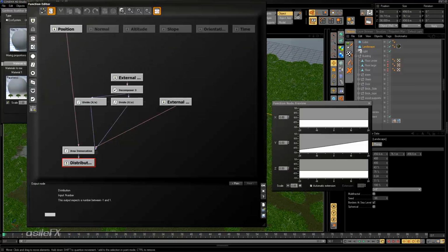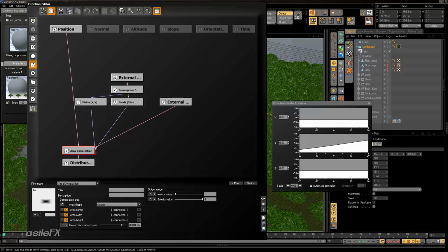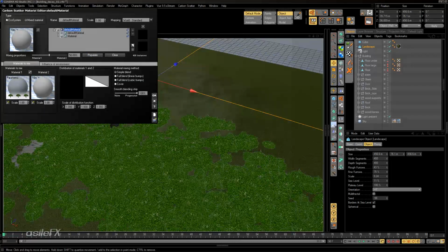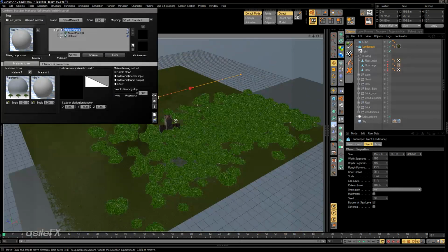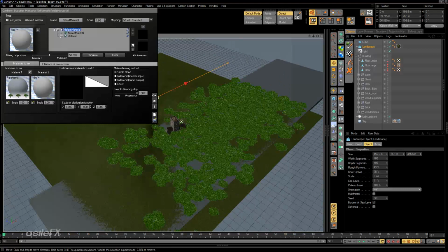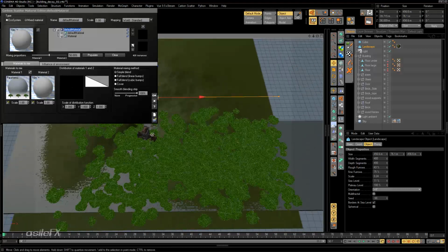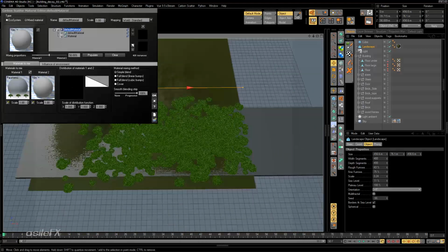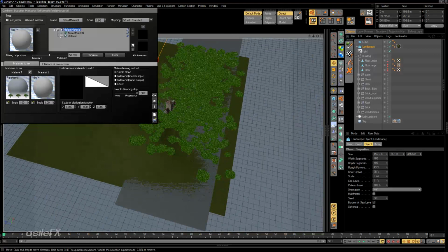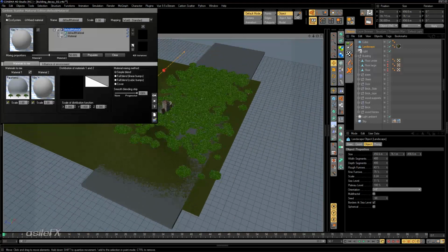If we did want to reverse this, we can go into the area demarcation filter, change the interior and exterior values, and flip them around. So now it populates within the box area. Keeping in mind it is smooth and it is expanding a bit more. Also, the way the gradient and the falloff is on the edges of this shape, since they're equal to begin with, then we are going to see more of a transition anywhere it's stretched out more.